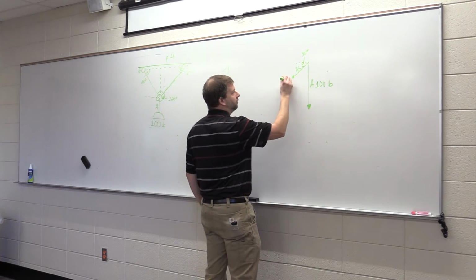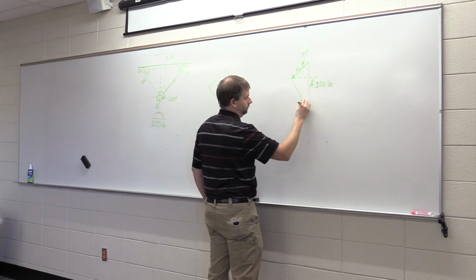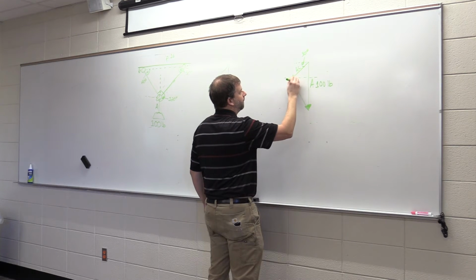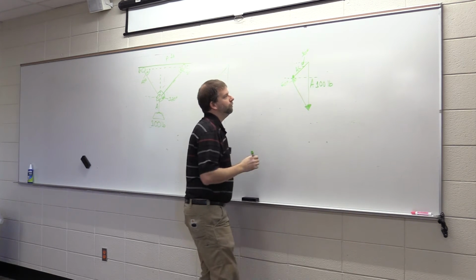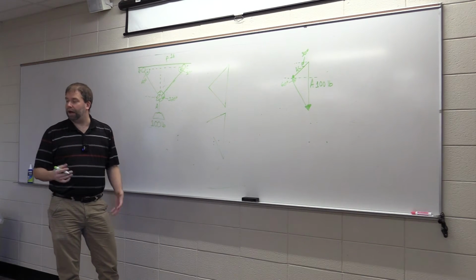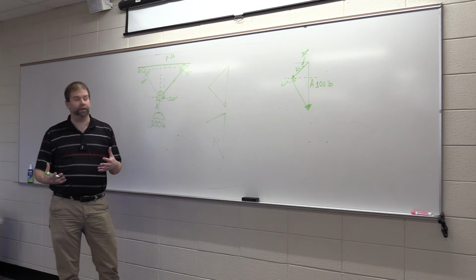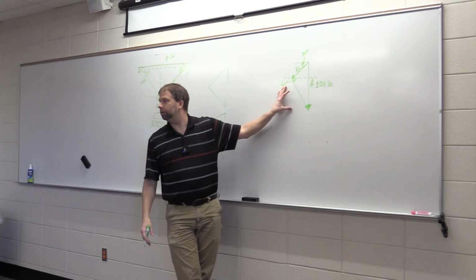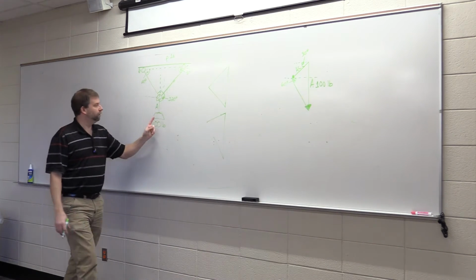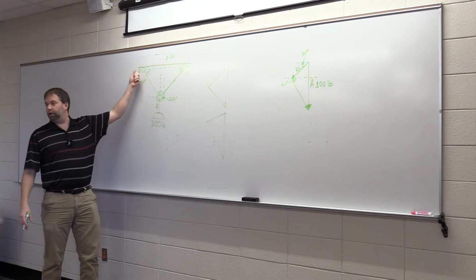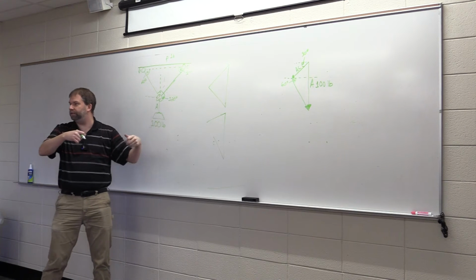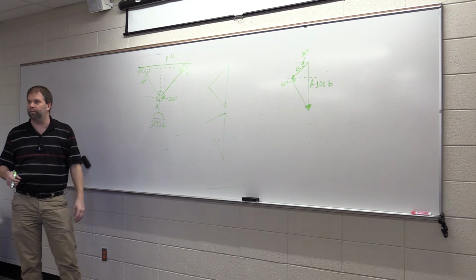So now if you come through and join those up, with that angle being 60 degrees, now we've got a closed force polygon. We've set up the condition where this thing will be at static equilibrium, which is what we want. We want to make sure that when we hang this 100-pound force, we don't tear that pin out of the ceiling, or worse, tear both pins out of the ceiling, crushing whatever equipment or people we've got below.